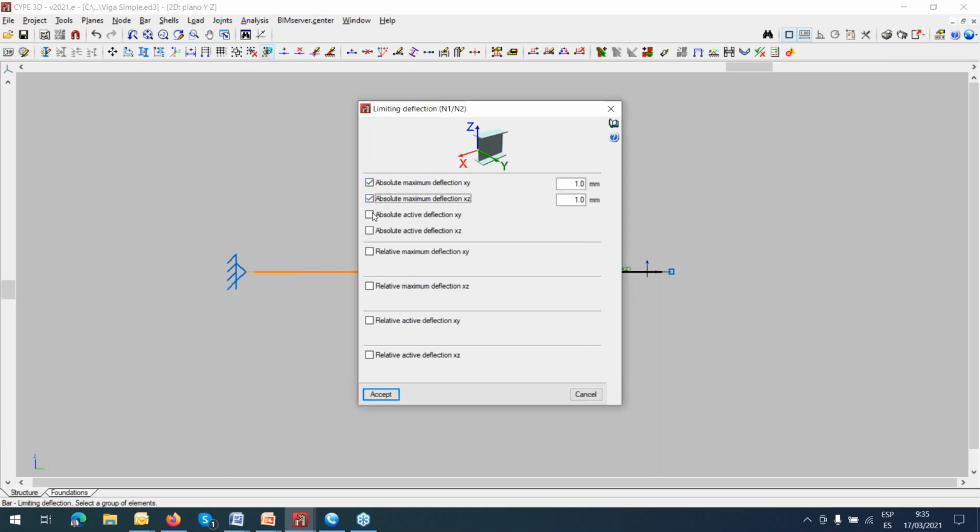But you gotta understand that if you display this, you have some numbers by default, but I think the relative maximum deflection goes by the normative, and you must check the normative. Just as an example, if you choose L divided by 500 means that you are using walls of very high quality, but if you go for L over 400 means that you are using poorer walls, something like that. The quality of the elements that you are going to use, you get exactly from the code reference. Normally, this limit, the relative maximum deflection, goes between L over 250 or L over 300, more or less. Okay, that's the maximum deflection.